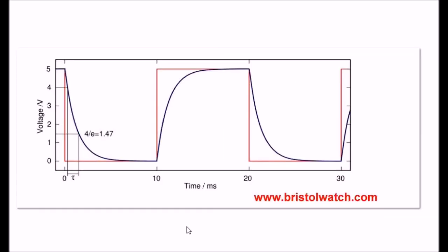When you switch that I/O pin on and off, and you're feeding the gate circuits of a bunch of MOSFETs, what you thought started out as a square wave, due to capacitive charge and discharge, is going to look like this. It's not going to turn on in a linear fashion. It's going to have a charge curve. This charge curve depends on the internal resistance of the transistors used in the drive source times the value of the input capacitance.